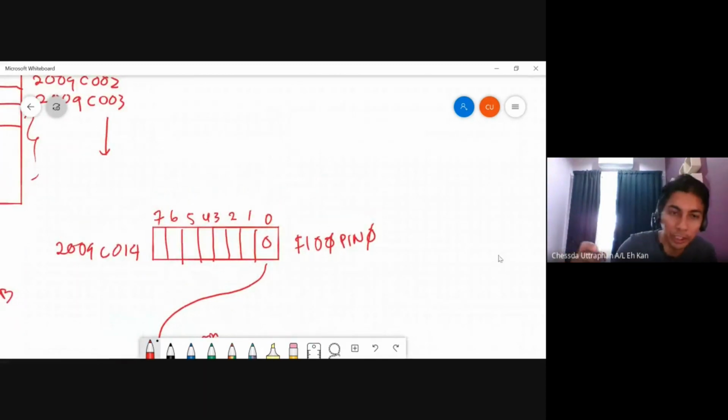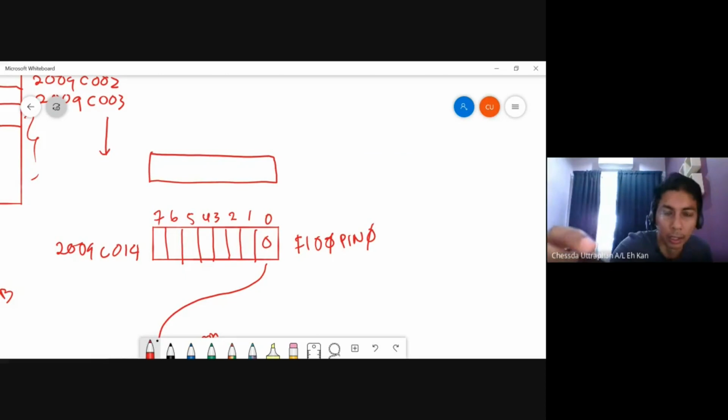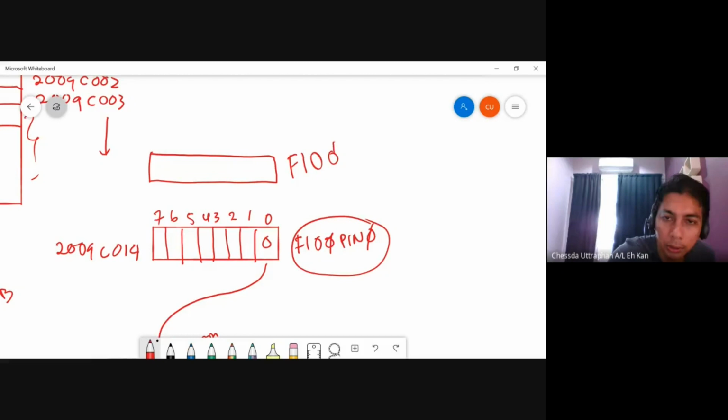To do that, you need another register. We call it the data direction register. This is actually a location in the memory also. So for byte 0, port 0, the data direction register that controls this port is named FIO0DIR0.